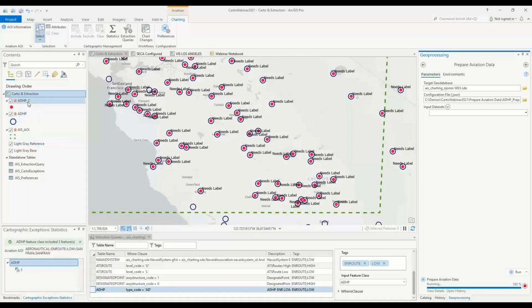So once this is done, we're going to open up the cartographic feature attribute table, and we'll see that those fields that we looked at in our JSON have been pushed to the main info field. And what that has given us the capability of doing is now we can publish this online, we can apply our arcade scripts, and it's feeding directly off of its own attribute table rather than having to continuously establish relationships across the database.